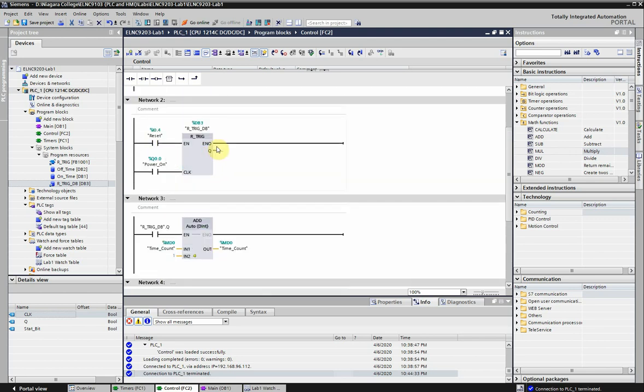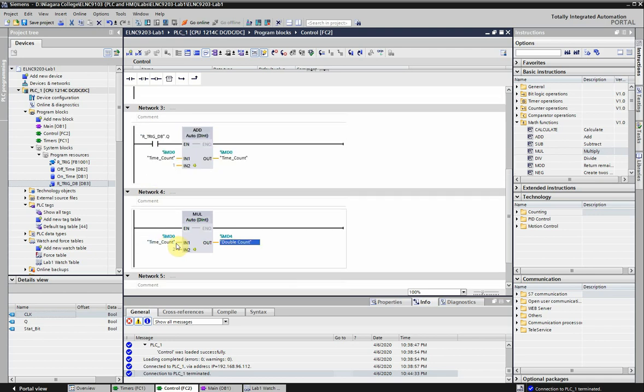And it only turns on for one scan after power on is detected going from 0 to 1. So basically every scan, this multiplication block will run. Since time count doesn't change, that's fine in this case. It's not going to create an iterative count like we had with this recursive add block.